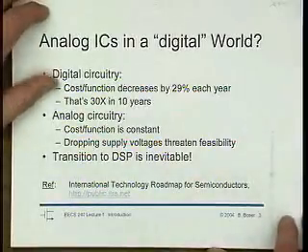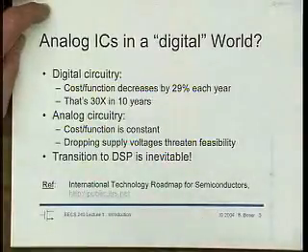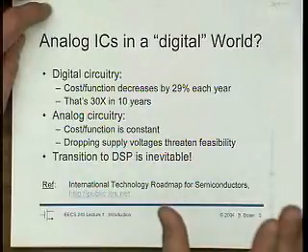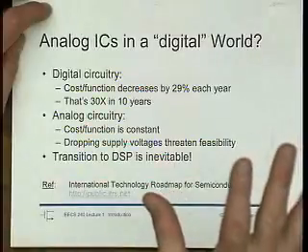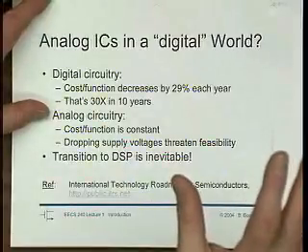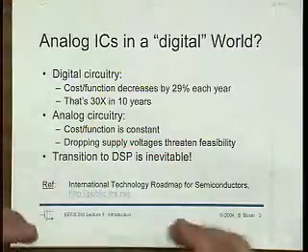Okay, so how does this digital stuff compare to analog circuits? Well, first of all, the reason why digital circuits get cheaper and better is that the technologies get better, right? Especially feature size, and we'll talk a bit about that later on. We'll see that analog circuits benefit from small features. If I have a 0.25 micron technology for my analog circuit, I probably can do a better job than in a 1 micron process. Okay? And for 0.12 micron, probably that is true also, although then it gets a little bit more complicated.